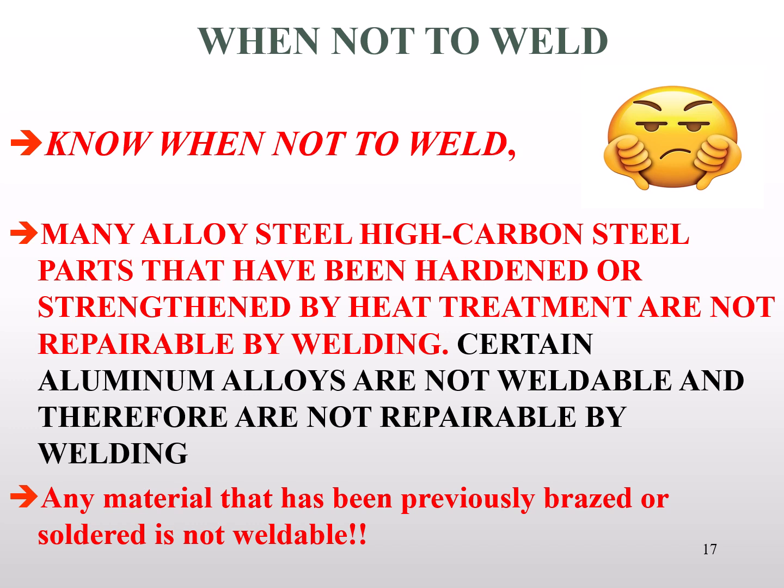Certain materials also are put through heat treating processes that make them undesirable to weld because we destroy the characteristic that made them eligible to be used in aircraft. As a rule, if it has gone through a heat treating process prior to being welded or after being welded, that's not something we can approach and repair in the field because it's going to require ovens and control processes we don't have access to.